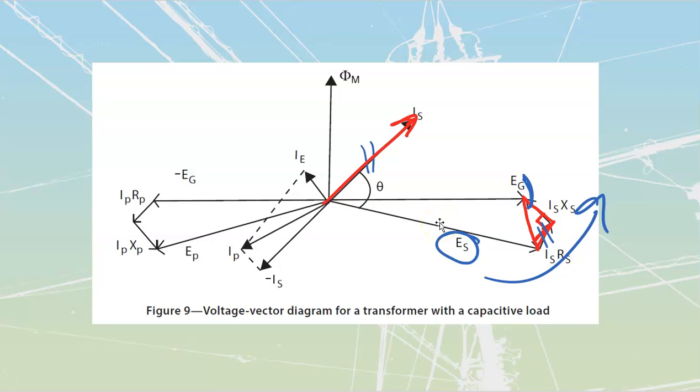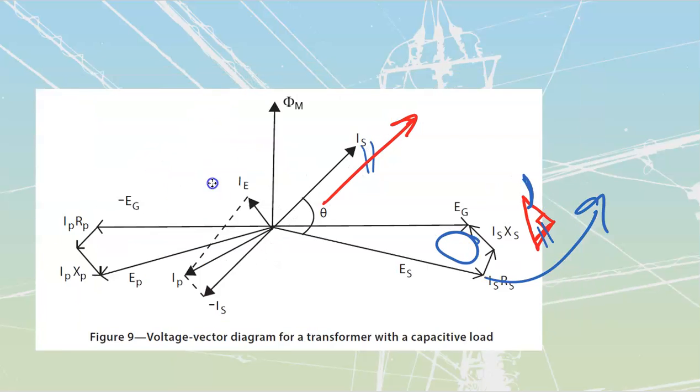I need you to go to the very last paragraph in this learning task and highlight that, because that's really most of this thing. Basically, it says, if we increase the power factor to a leading power factor, the transformer terminal voltage is going to go up. This is a bad thing because it means that everything that's attached to it, your house, your neighbor's house, your factory, your neighbor's factory, is all going to see way too much voltage. So let's sum it all up into a couple of sentences.